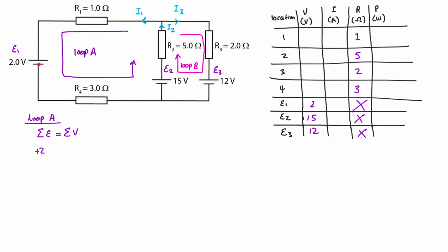That's the EMF. It's going to lose some energy here, which I'm going to write when I'm writing the right side of the equation. Then it's going to go through another battery over here. But this time, it's being pushed away from the negative side and pulled in this direction. So this cell is actually pushing it in the opposite direction, so I can't use a positive value. I have to use a negative value here. So I'm going to go negative 15.